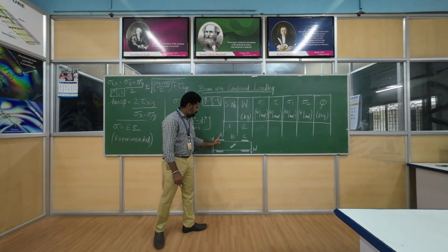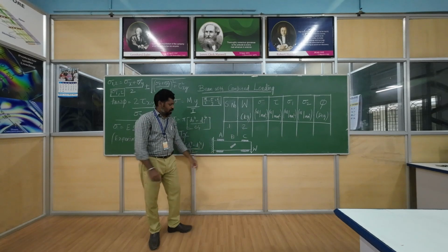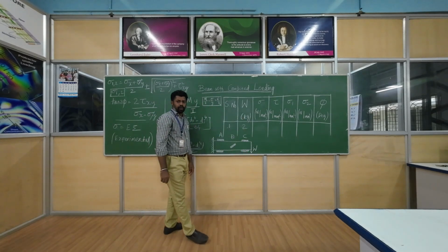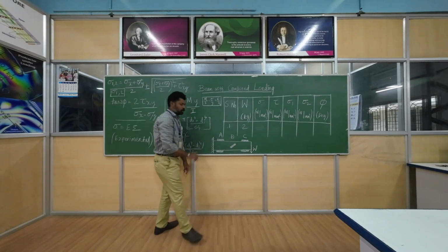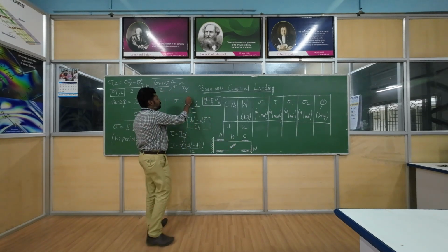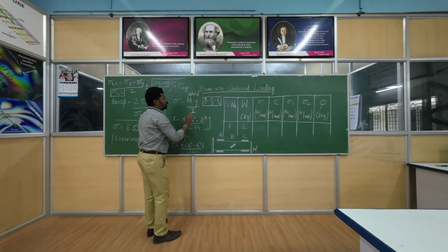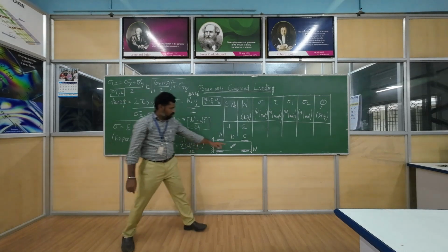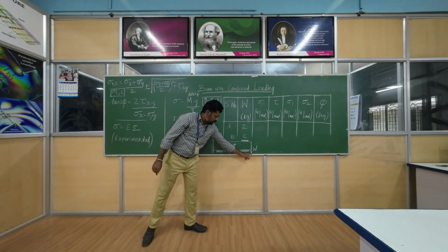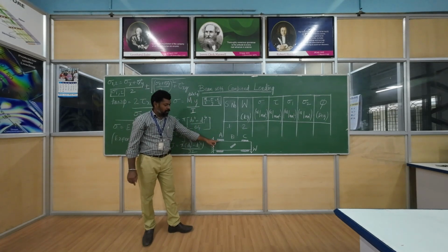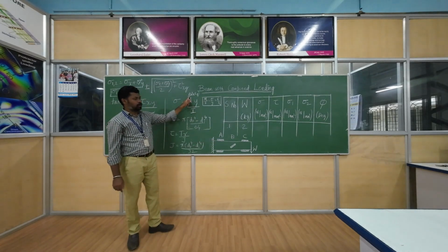So see here, this is a typical cantilever beam. I am going to compute the stress at section A. So what is moment? The load into the particular distance. So here M is nothing but W into L1 will give the moment. So when I apply a W at the free end, I get a moment of W into L1 at section A. So now I got the moment.